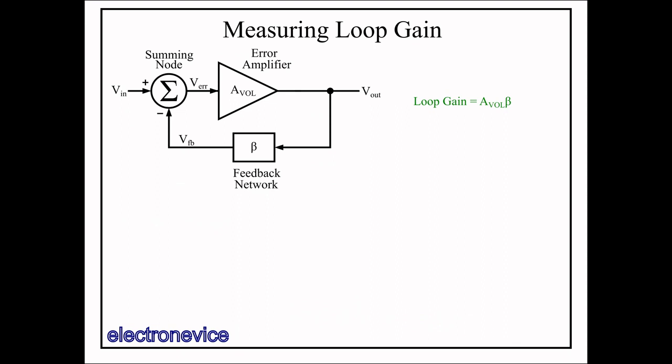Briefly recalling the general structure of feedback circuits from the previous episode, we know that the loop gain is equal to the open loop gain times beta. We need a way to extract the loop gain from a given circuit in LT-Spice. It's best if we can do this while maintaining the feedback loop, as breaking the feedback loop will often lead to weird nonlinear problems, such as the input offset voltage causing the output to rail when Spice is calculating the DC operating point. So we insert a small AC voltage in series with the connection between Vout and beta, and zero the input voltage signal.